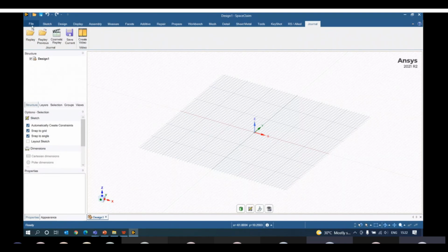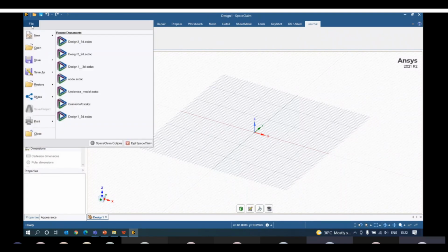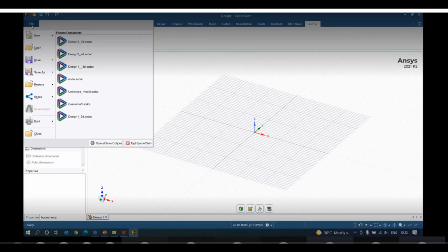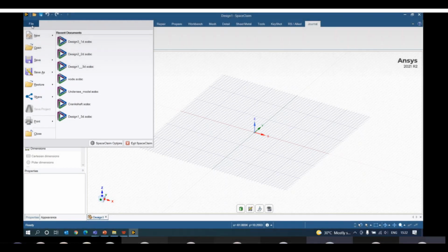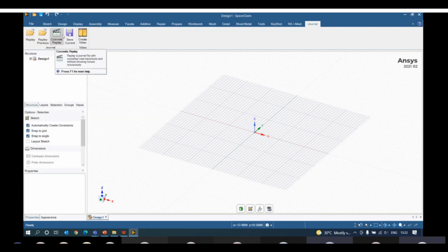So let's begin. The first important thing, whenever you're working with CAD or any designing model, is the sketch plane. Sketch plane is most important, right? So what is your sketching plane? Generally, I would suggest that whenever you work, make XY your sketch plane.